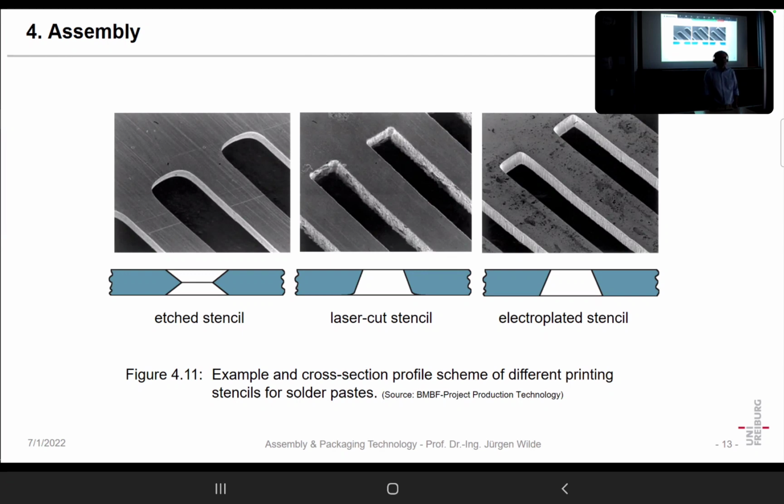Yeah, okay, why? Time? So, yeah, that's not really the reason, but to the left and to the right, for these processes you always need a photoresist. You must expose the resist, develop it, then do the etching or plating, maybe some back etching process. And again, that always needs some special, like the resist.